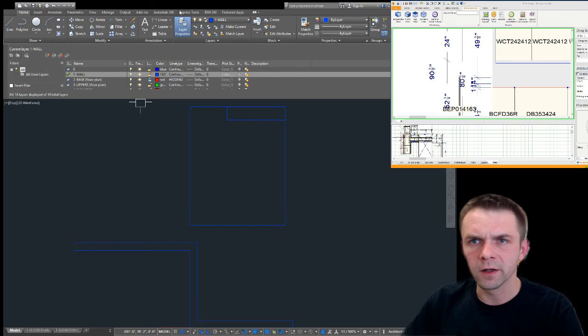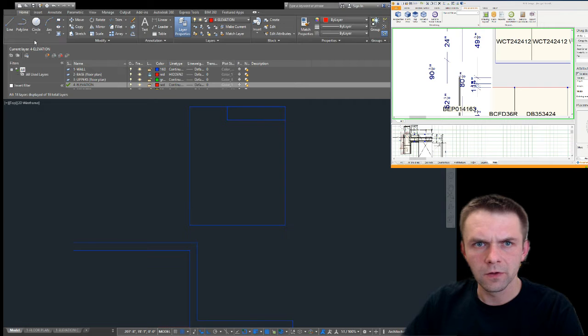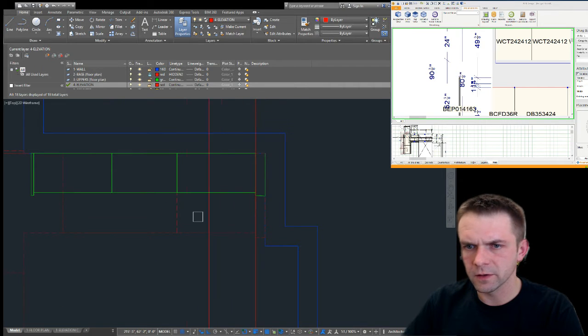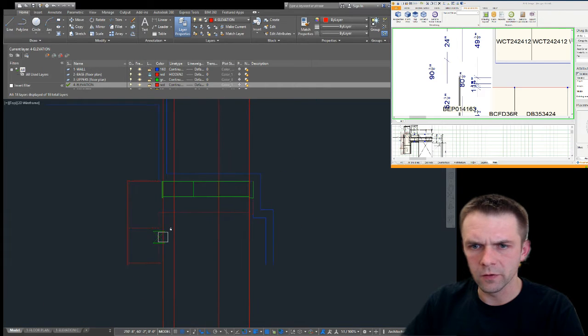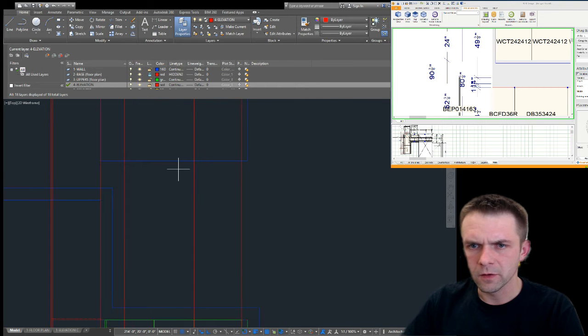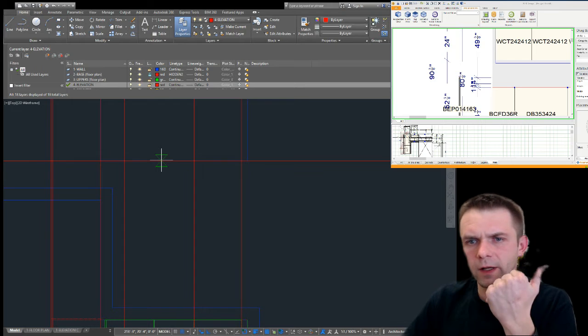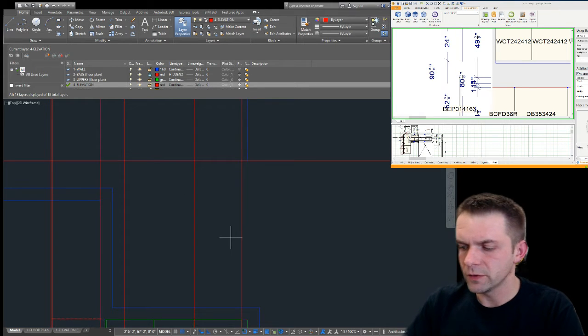So we have our elevation. We click here. We select elevation. Draw. Vertical, V for vertical, and then I just select the lines that I need transferred. So let's do the base cabinets first. Then select, repeat the command, click on a line, just drag it to the left, and now offset 425.